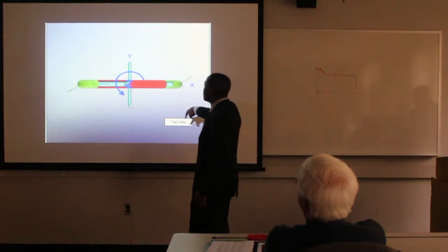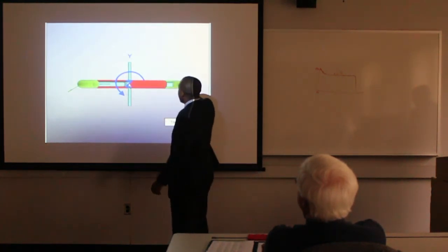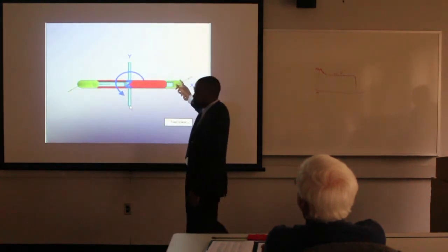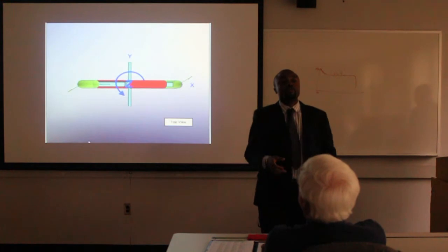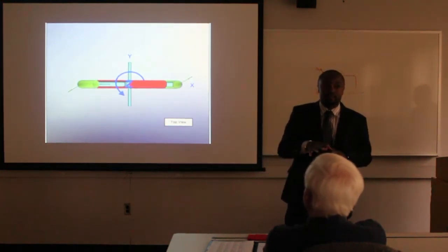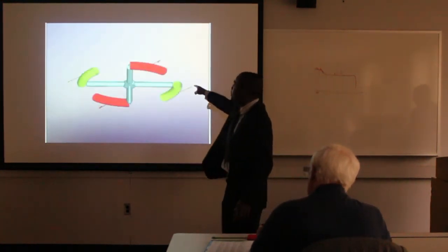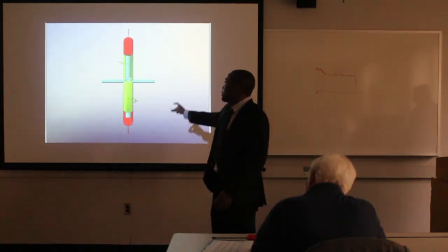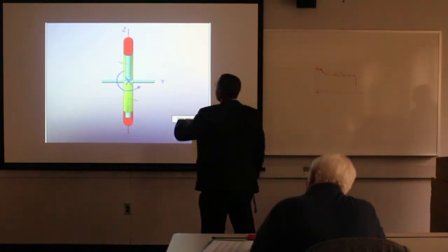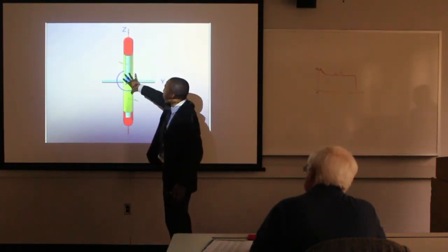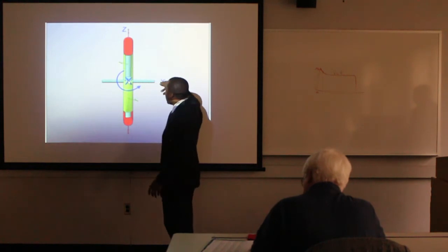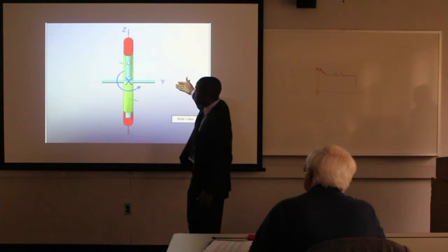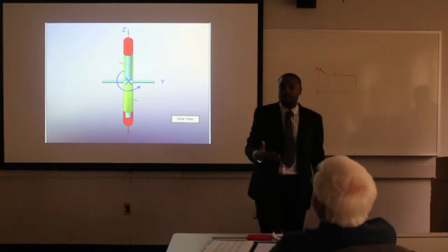But when we have the mass spinning, there's a force created in the Z axis. That force is called precession. It's that force that we need to actually balance out the system. The force and its direction depend on the direction of the spinning mass on the top, and it can be switched. We add that because if you use Z and Y, with the motor horizontal, they call it a horizontal gyroscope. You can use that, but for our case, we use a vertical type gyroscope.